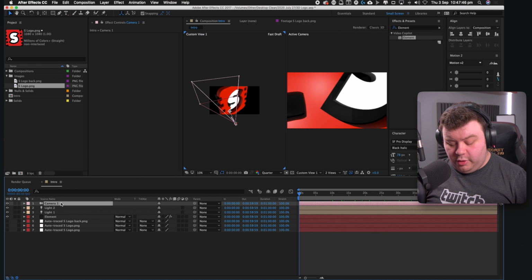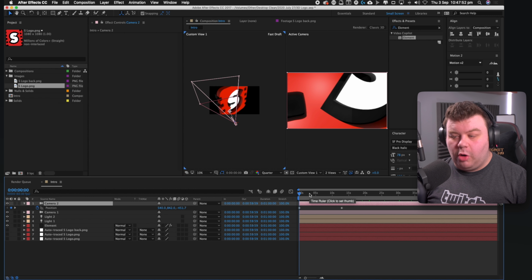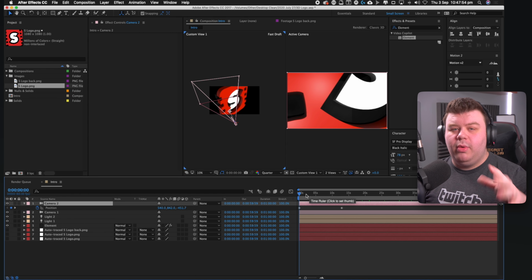So say, for example, you want to have multiple shots cutting around the logo like I did in the finished video. What I did was I just duplicated this camera and then tweaked the keyframes for this top camera, because After Effects will only look at the layer of the first camera. It will only look as far as the first camera down.